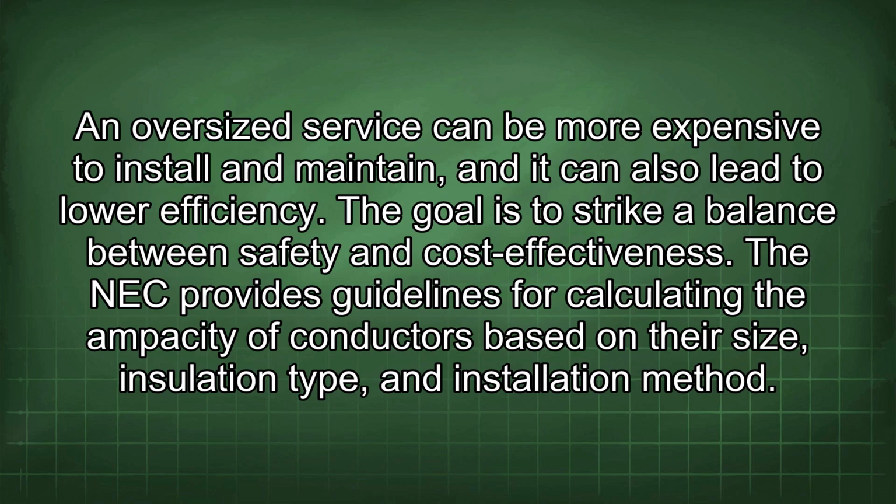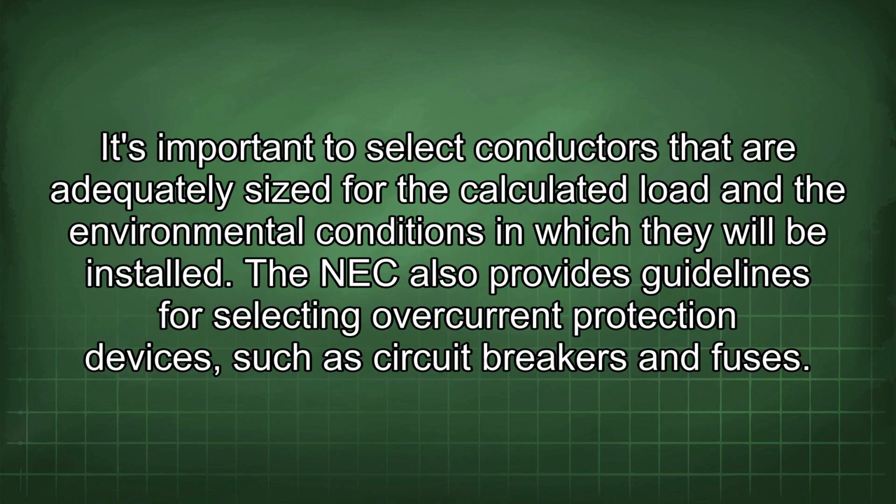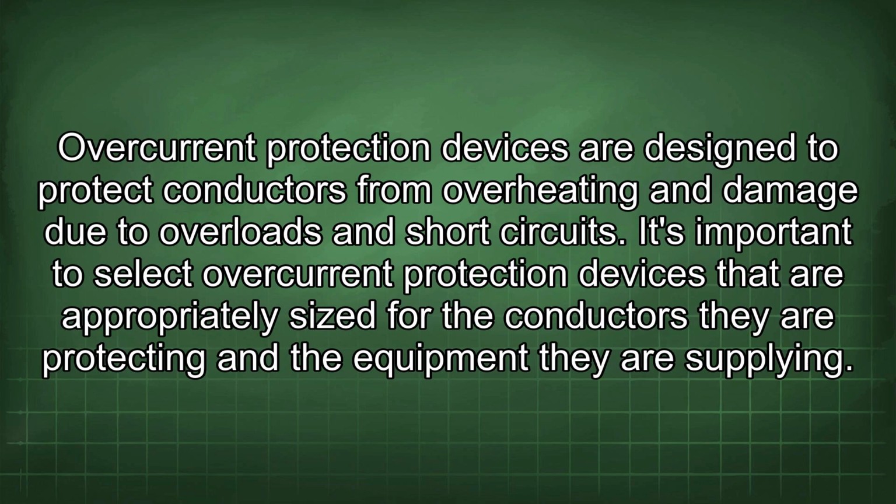The NEC provides guidelines for calculating the ampacity of conductors based on their size, insulation type, and installation method. It's important to select conductors that are adequately sized for the calculated load and the environmental conditions in which they will be installed. The NEC also provides guidelines for selecting overcurrent protection devices such as circuit breakers and fuses. Overcurrent protection devices are designed to protect conductors from overheating and damage due to overloads and short circuits.